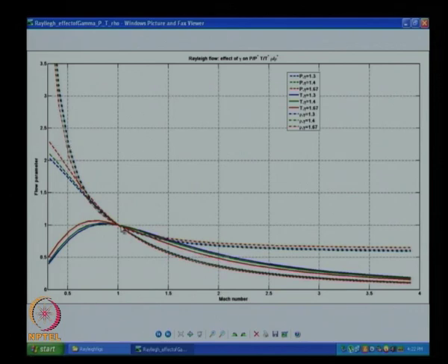As I go towards M equal to 1, the change is not as high, but it is still changing at M equal to 1. It is not slope 0 there. The change in density is very high for very low subsonic, and pressure is not changing so much. So, what should happen now? P equal to rho RT, so temperature should compensate for this change. The density drops a lot, temperature has to increase so that the pressure drop will be matched. That is why temperature is rising.